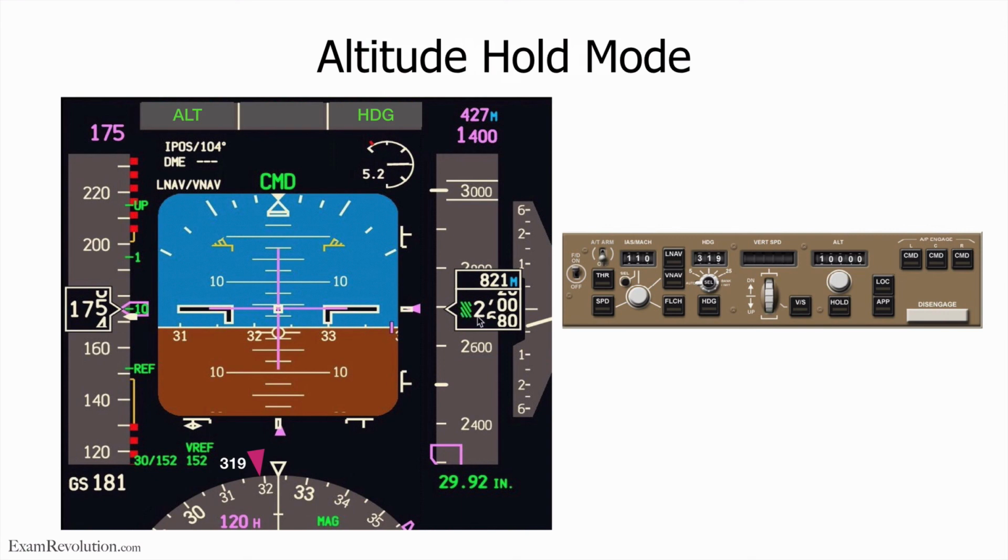That means it will maintain this altitude that it is currently at, or it will show alt when you have leveled off at the altitude that you have set there. So let me give an example. If you were in the descent like this aircraft is now, right? You can see it's descending here on the VSI. It's going down to 1,400 foot. It's passing through 2,680 foot roughly, right? When it gets to 1,400 foot, it will start showing alt because it will level off at 1,400 foot.